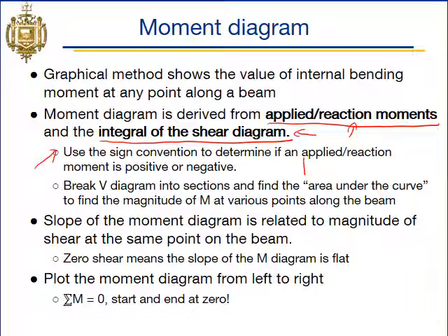One case we see a lot is a cantilevered beam, right? We see a lot of cantilevered beams fixed on the left end with an applied load out here. So this is going to bend like that, so sad face. In cantilevered beams, we have a reaction moment like this, and that's actually going to be a negative internal moment, because we get negative bending. So just remember that. You'll see that in the examples. With cantilever beams, with this negative bending, our internal moment will actually be negative.